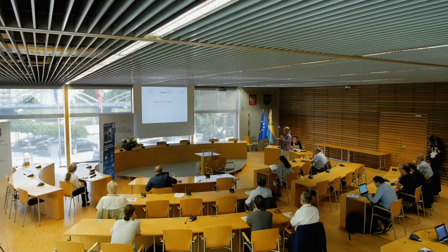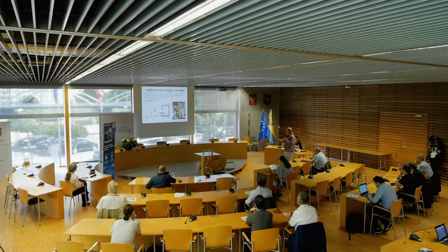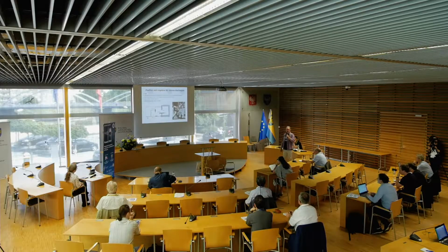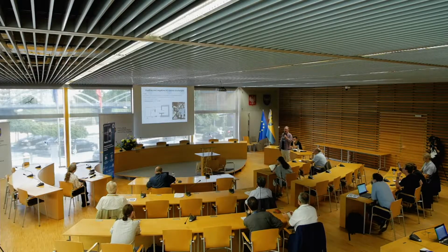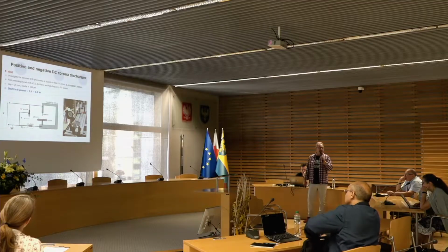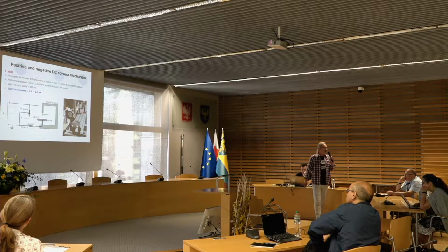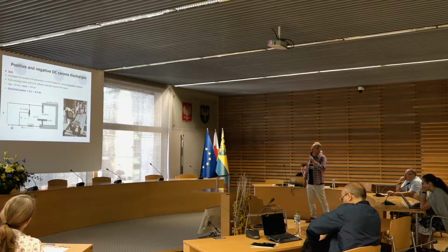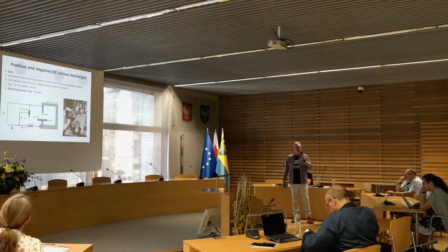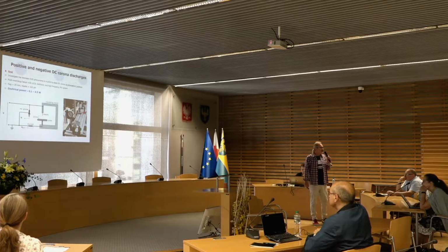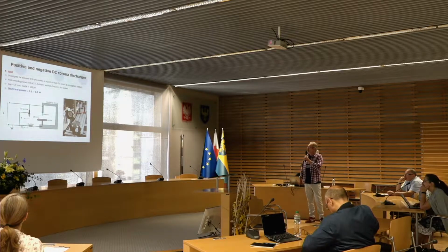So first, I'm going to speak about needle-to-plate corona discharge. In this study, the goal was to investigate the transient phenomena occurring in a discharge produced between a point and a plate with negative and positive DC high voltage. For that, we developed a multi-methodology bench with ICCD, Schlieren visualization, and particle image velocimetry. I will speak about that because maybe you don't know what it is.